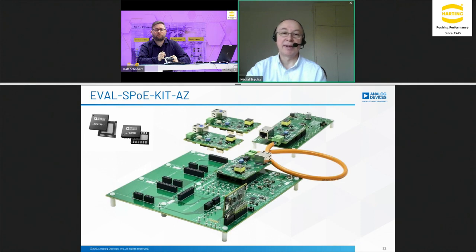You can see the motherboard for the PSE controller, which has 5 channels, so you can plug in 5 modules for data and power coupling. By default it serves 10BASE-T1L data, but the PSE and PD controllers work with any single pair technology up to gigabit.